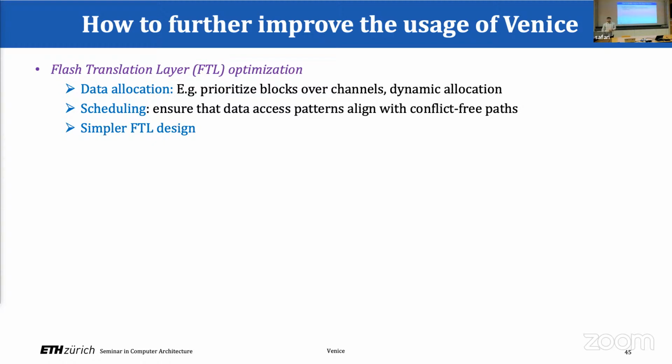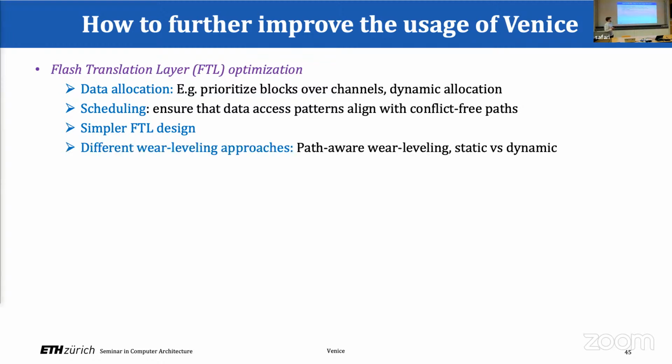Further research can certainly be done in simpler FTL design and different wear leveling approaches. Basically, don't distribute statically over all flash chips, but maybe dynamically adjust based on how much they are used or how much they are erased, and increase the lifespan of the SSD by using other approaches of wear leveling.